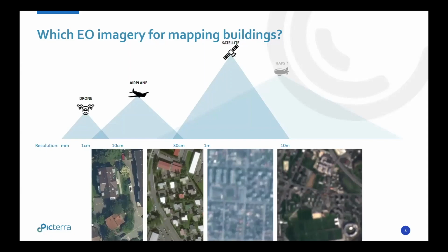So yeah, building areas. You will have difficulties to catch the individual buildings if they are too small. Once you move down towards the meter resolution, you will start to be able to localize individual buildings, but that doesn't mean that you get the building footprint. In order to move to the building footprint, you will have to go to a sub-meter resolution, 50 centimeters, 30 centimeters, where you will really be able to get the boundary of the building, which, depending on the application, you need.